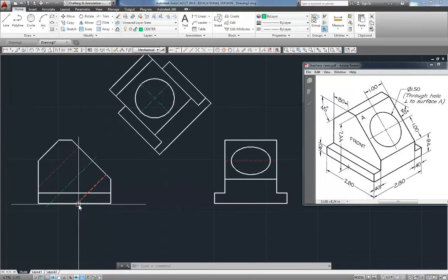So imagine I have part of the circle here and part of the circle here. If you slice a cylinder at an angle, you get an ellipse. And we actually get two pieces of ellipse here. And they would form one tall ellipse. So to get the hidden lines for this, there's going to be an elliptical arc back here that is this tall, right to there. So this gets rather tricky.